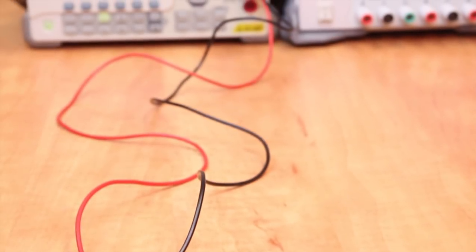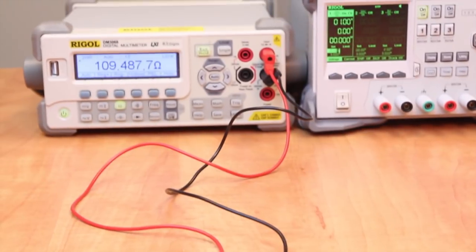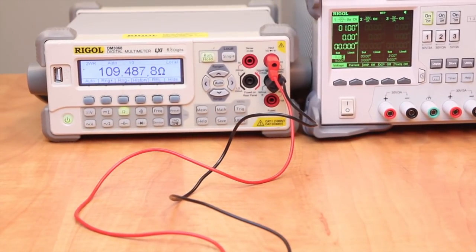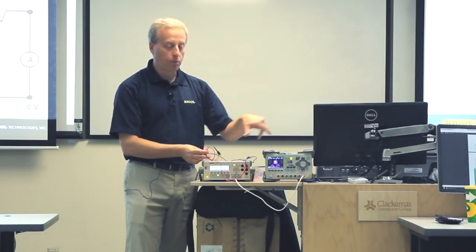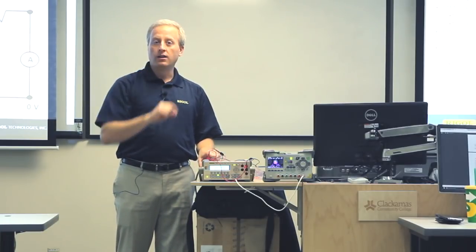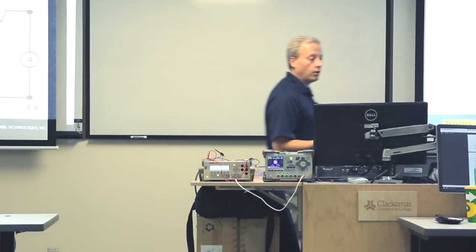So, as an opposite to the loading problem, if this were a small resistor, like 1 ohm, then we might see 1/10 of an ohm from this wire and 1/10 of an ohm from this wire being added to that measurement. What 4-wire does is separate those 2 sets of wires so that the current is flowing in one loop and the voltage is being developed on the other side, but there's no current flowing through the leads. So you don't get additional resistance added from there.